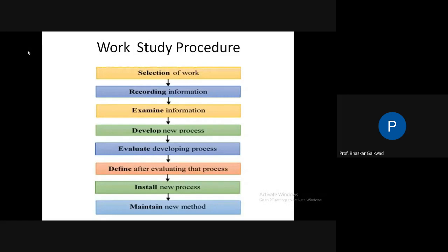Once this is over, we have to get it fixed on the VMC machine for drilling the 6 holes of 7 mm diameter, and there is a jig. After making the program on the VMC, we go for drilling those 6 holes. Once the 6 holes are drilled, the product is ready for dispatch.